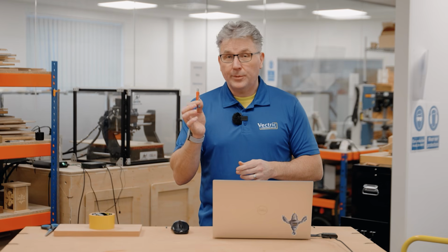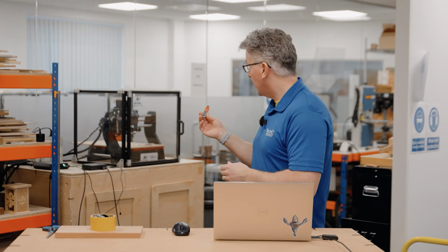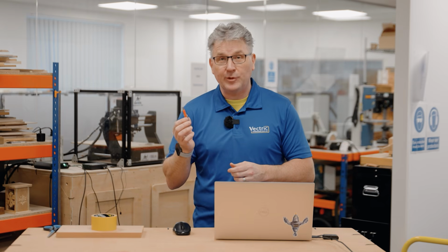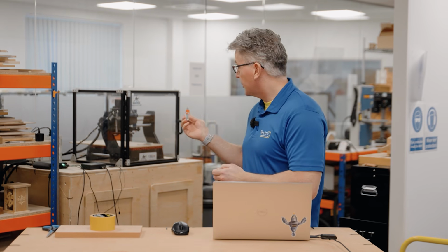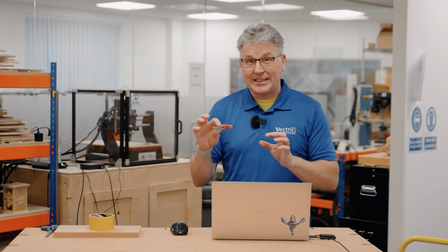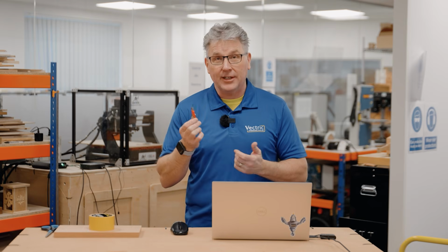Okay, I've got my toolpaths all saved off onto my USB drive so I can bring them over to our Next Wave CNC. Now this CNC is an interesting way to interface your USB drive with the actual controller. So we'll need to plug it in the side of the pendant and just load our file from there, which actually is pretty simple and easy to do.